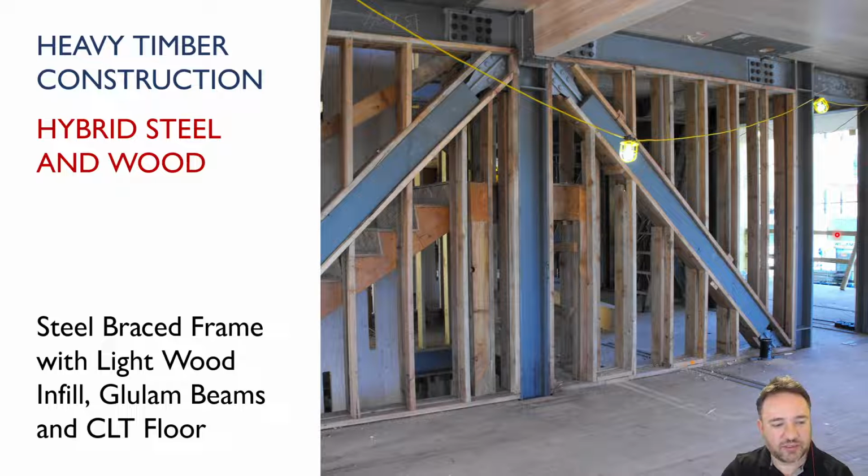Steel is a natural system for lateral load resisting, and especially here, these are buckling restrained braces, which is a high performance earthquake system. So you can get the benefit of that high performance earthquake system, but at the same time get the other benefits of wood in terms of constructability, aesthetics, and light weight.